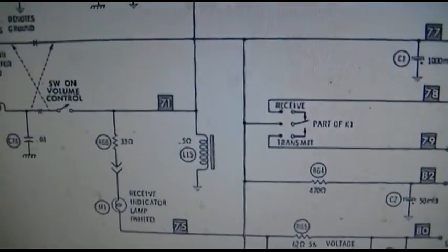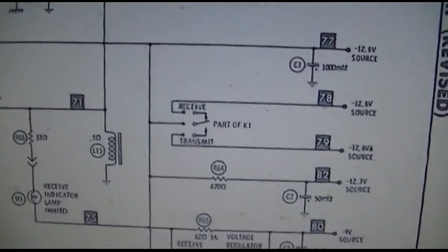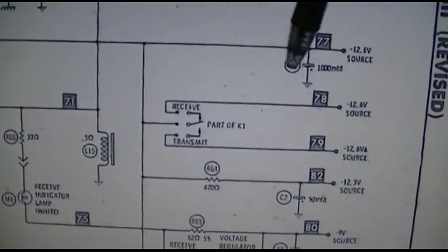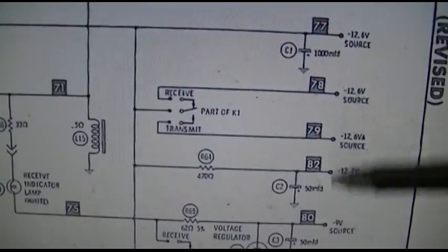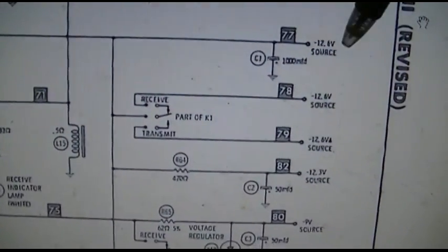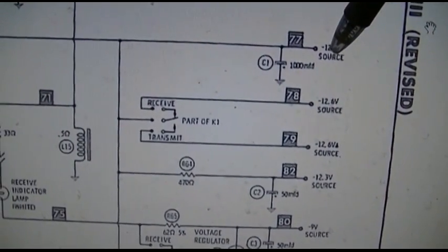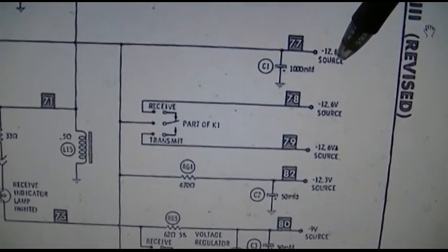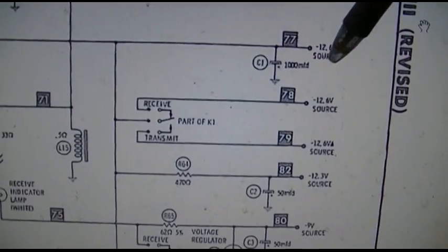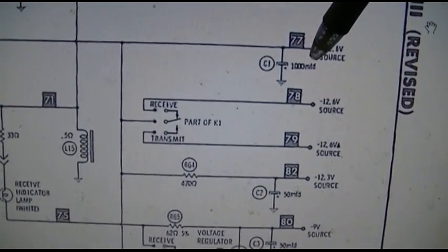Right, so this is kind of what I was talking about, the power supply. You have the power coming in here, and then this is where it branches off here. So you could see whatever this connects to would be your direct feeds that would most likely cause a short. And of course there's the capacitor right there that was causing the problem.